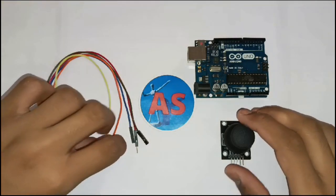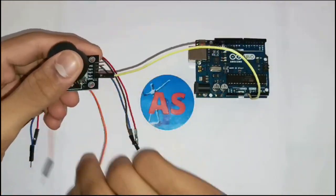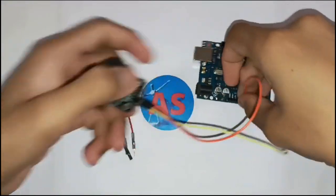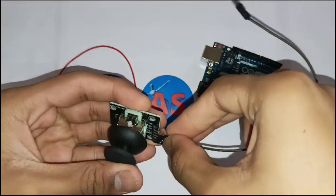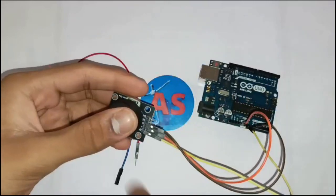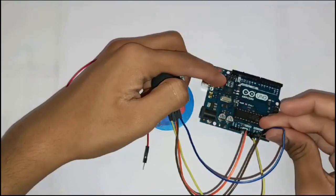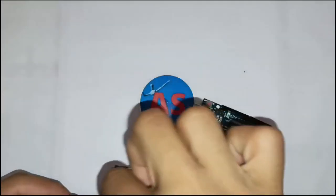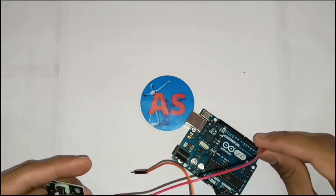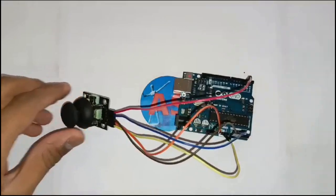Now let's make the circuit. So first we will connect GND pin on PS2 joystick with GND pin on Arduino. Then we will connect plus 5 volt pin on PS2 joystick with plus 5 volt pin on Arduino. Then we will connect VRX pin on PS2 joystick with A0 pin on Arduino. Similarly, we will connect VRY pin on PS2 joystick with A1 pin on Arduino. And at last we will connect SW pin on PS2 joystick with D2 terminal on Arduino. So this is the overall circuit.